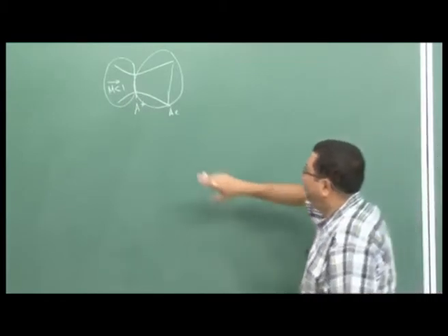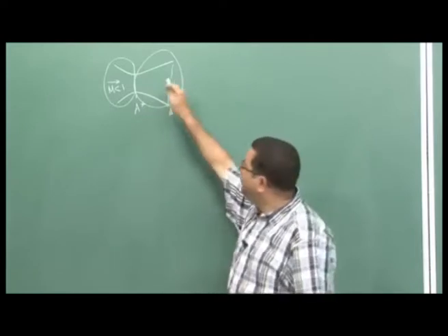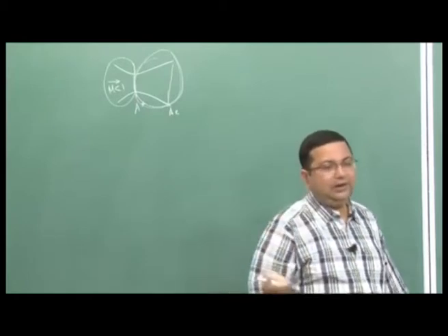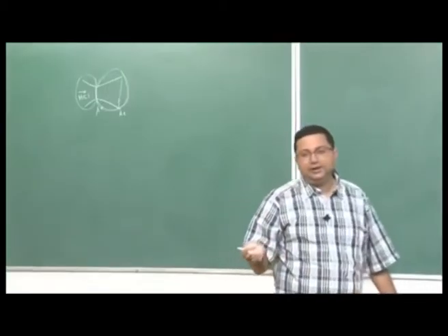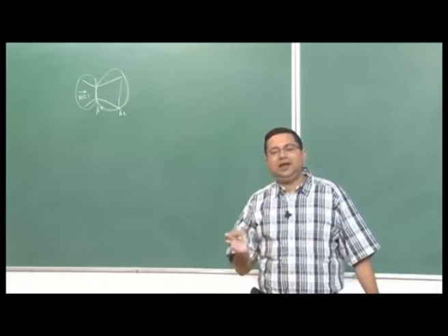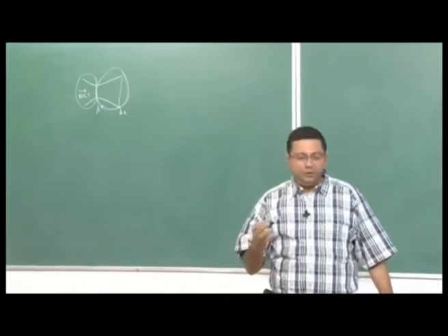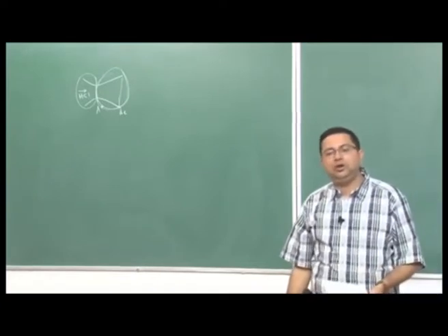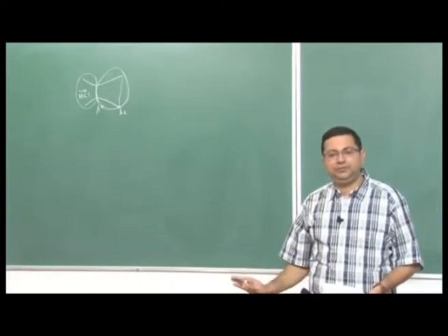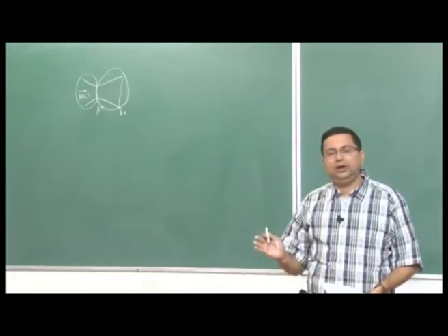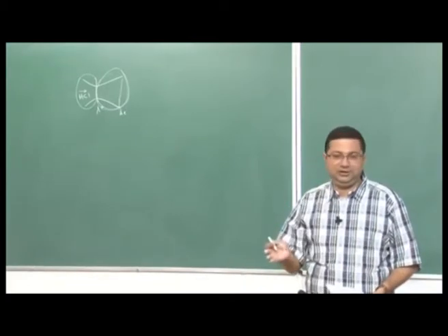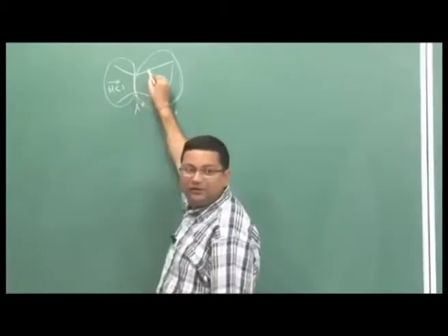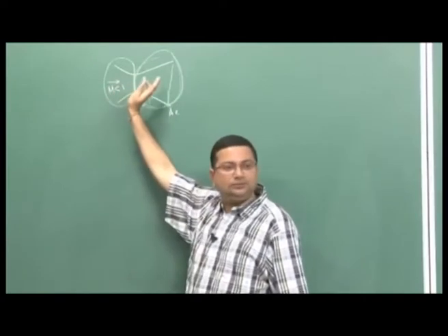The shape of the diverging portion is, however, important. Here also the flow is accelerating, so it is a favorable pressure gradient, but how much acceleration there will be, whether there will be a shock wave or not, or whether there is a huge pressure loss or not, all depend on the shape, because the area ratio at every location is important. So, at every area location we have to have a given area ratio, which will give us the flow.